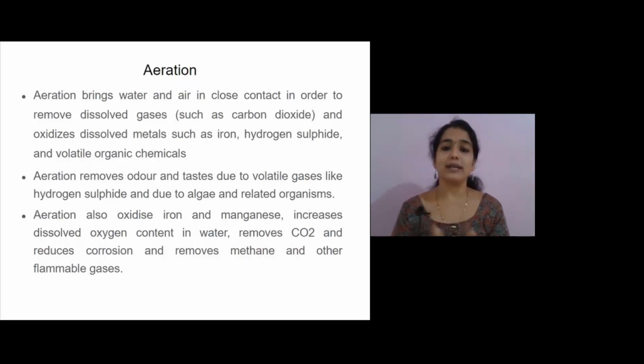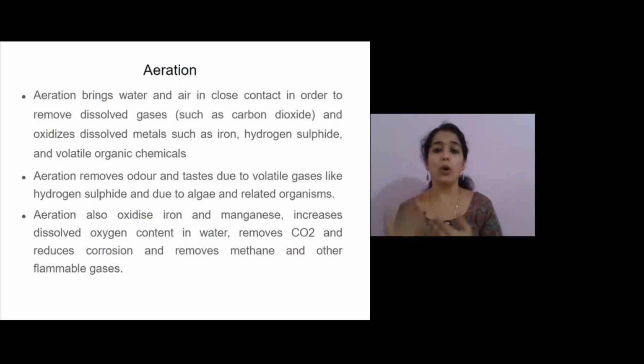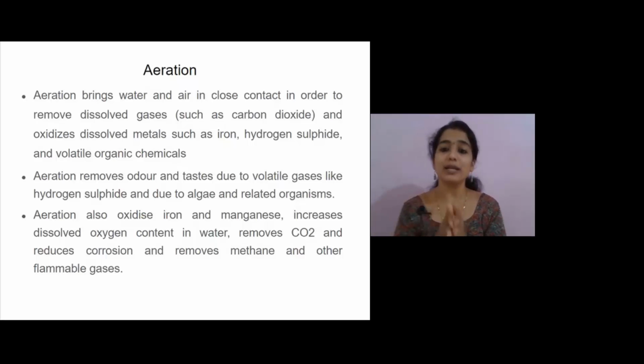Aeration brings water and air in close contact in order to remove dissolved gases such as carbon dioxide, and oxidizes dissolved metals such as iron, and removes hydrogen sulfide and volatile organic chemicals. The air diffused in the water will remove all these impurities up to an extent from water. Aeration removes odor and taste due to volatile gases like hydrogen sulfide and due to algae and related organisms.